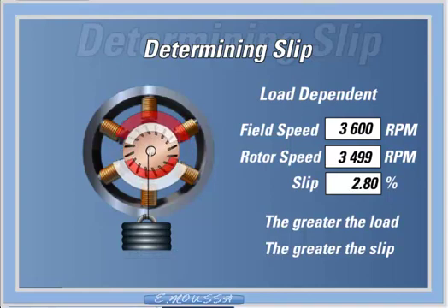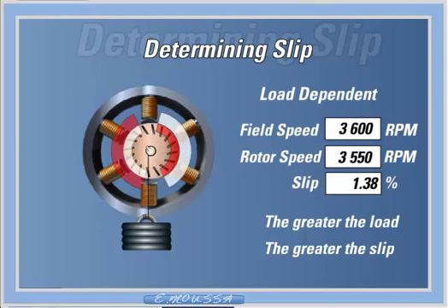If the load were to decrease, the rotor will speed up relative to the stator's rotating field, and as a result, the lines of flux in the stator's magnetic field will cut the rotor bars at a slower relative speed, inducing a smaller voltage in the rotor bars, which in turn induces a lower rotor current. This lower rotor current produces a smaller and weaker rotor field, which interacts with the stator field to produce a lower torque to overcome the decrease in load.